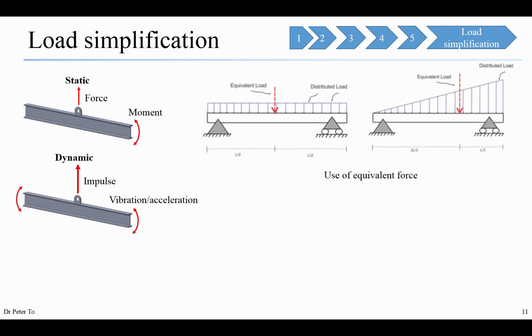The governing equation for the finite element method in statics is Ku = F, and you may know it from Hooke's law, F = Kx. In dynamics, it will be Ku + m d²u/dt² = F(t). And in modal analysis, you have (K − ω²m) times the shape mode vector equal to 0 for free vibration, where K is the stiffness matrix.